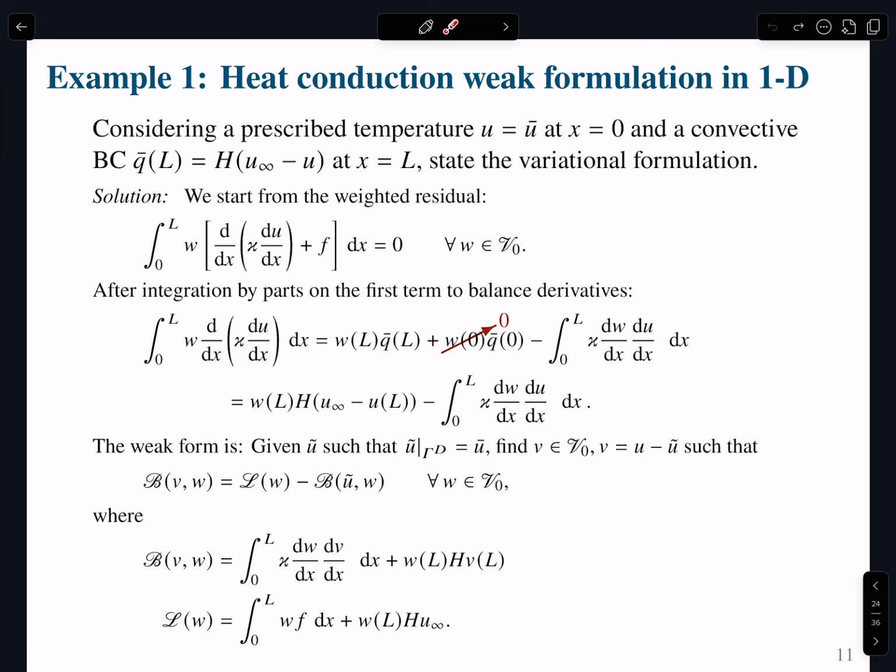I do the Bubnov-Galerkin approach, where my test functions and my trial solution eventually are going to be chosen from the same space. I get symmetry, and again, the same story. Symmetry leads to nice properties: a symmetric stiffness matrix, and fewer operations if I want to solve with a direct solver, with Cholesky factorization, all these things.